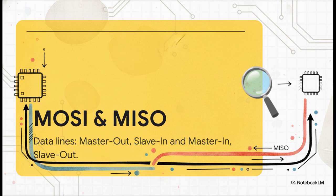MOSI stands for Master Out, Slave In. It's the wire carrying data bits from your main controller down to the peripheral. Then you have MISO, which is Master In, Slave Out. That's the wire carrying data from the peripheral back up to the controller. Depending on the hardware vendor, you might actually see these labeled a bit differently on datasheets because, as we'll see later, SPI is pretty loosely defined. But functionally, it's simple. 1 wire sends data out and 1 wire brings data back.